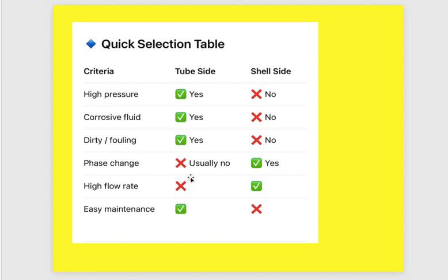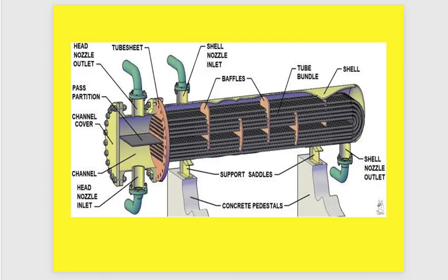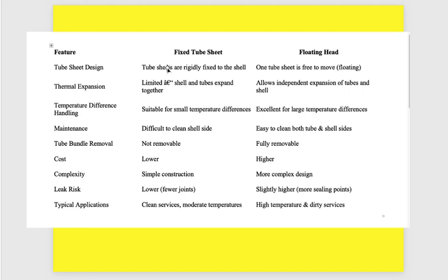So at this point we mentioned the main composition of the heat exchanger, shell and the tube. Here this is the main component for shell and tube heat exchanger, and we described the U-tube type and what is the advantage of this U-tube type. And we mentioned fixed tube sheet and the floating head. And finally, I want to make a description or comparison between both of them, simply to guide you when to select a floating head or choosing fixed tube sheet.